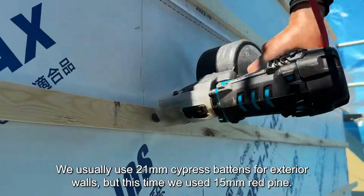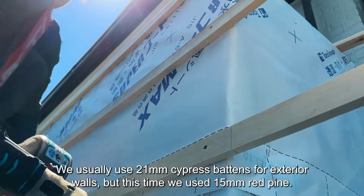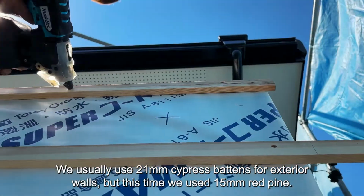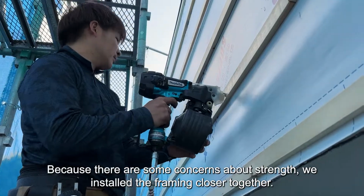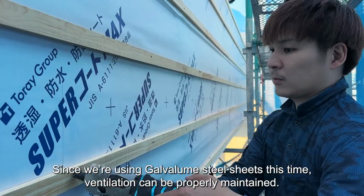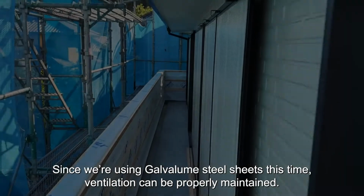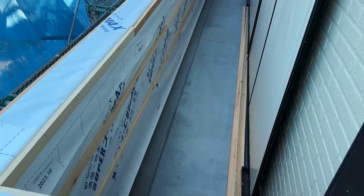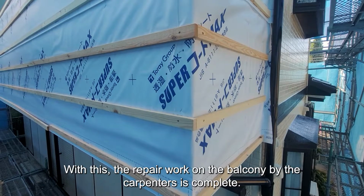We usually use 21mm cypress battens for exterior walls, but this time we used 15mm red pine. Because there are some concerns about strength, we installed the framing closer together. Since we're using Galvalume steel sheets this time, ventilation can be properly maintained. With this, the repair work on the balcony by the Carpenters is complete.